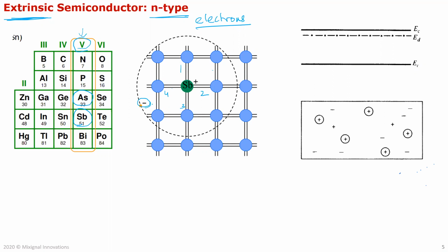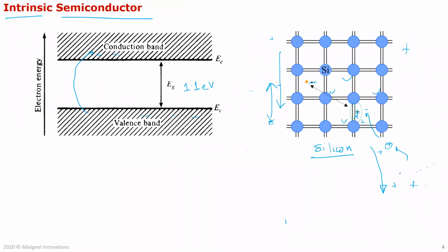So that electron has enough energy to actually conduct now in the current. And obviously, if it goes away, then it will leave a positive charge. But this is a positive charge which is immobile, in the sense that, unlike in the silicon where you are forming a bond, the bonds are formed. So if you look at the charge, it's just a positive charge, but it cannot move in the sense that another electron cannot come here and take its place because it's a free electron. In your previous case, in this case, you are breaking a bond.